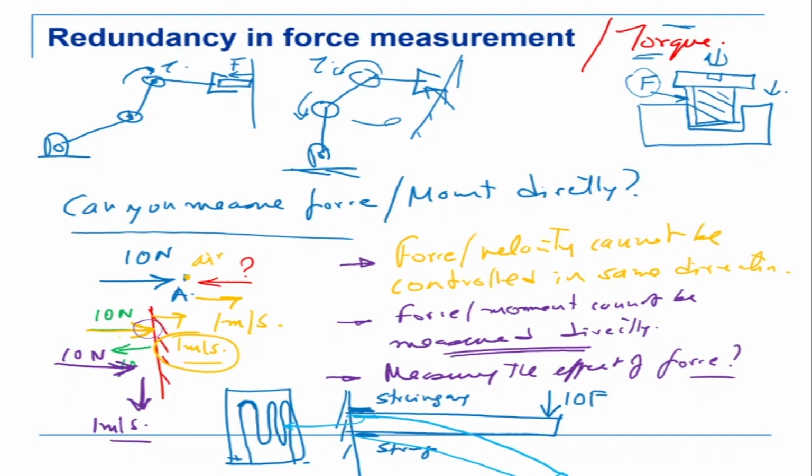If the resistance increases, less current will flow through it. So I can calibrate this like this, say force versus voltage. I start off with say 1 Newton, 2 Newton, 3 Newton, 4 Newton, and I see what is the voltage which is flowing through the strain gauge. Then I plot it, and I fit a straight line. So if I get an unknown voltage, I can very easily see what is the corresponding force being applied. So if I have to calibrate the strain gauges, load cells as force sensors, they're exactly the same.